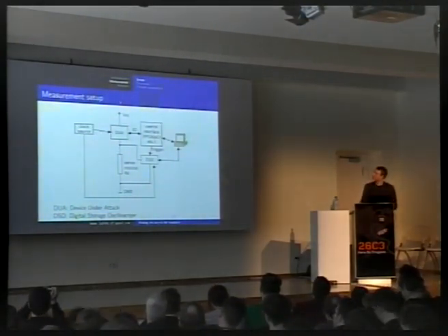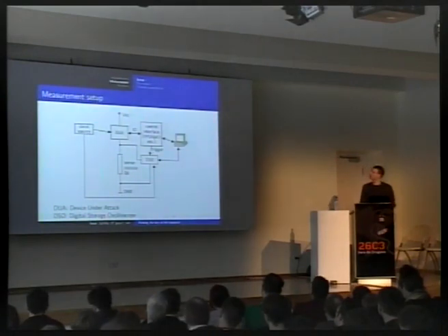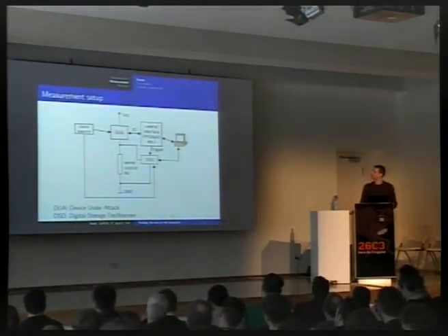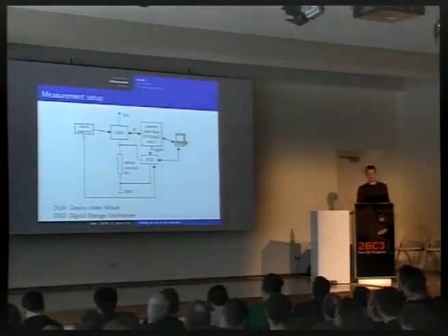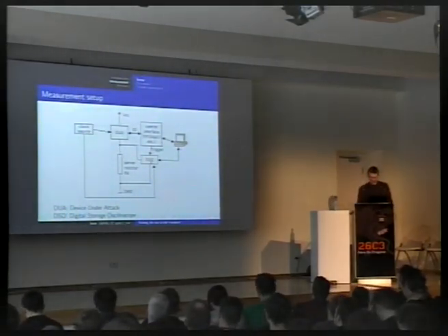We don't have to craft specific plain text, but they should be mostly random. Now the device is powered, of course, and we need to measure this power. This is done using a sensing resistor. We measure the voltage drop across this resistor with the digital storage scope, and we can read the power samples from this scope afterwards. We also should use an external clock source to synchronize the device we want to attack on the digital storage scope. I'll come back to this later.